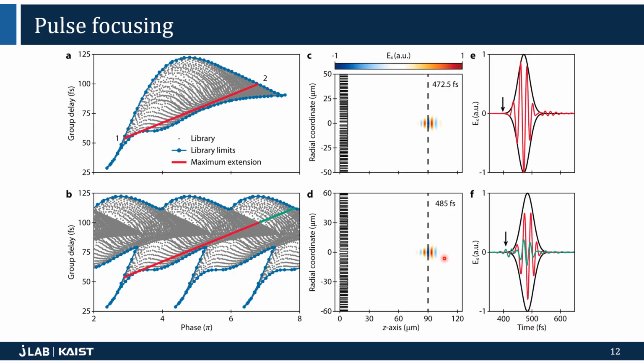But we also see a slight elongation of it. We attribute this to 2 reasons. First, we have an abrupt phase jump in the B-type lens system. This could cause irregularities in the wavefront. Second, the meta elements from the extended part of the library, we found that these exhibit less ideal wave transmission behavior due to the excitation of higher order modes. It is, however, not particularly strong. However, these things should be considered if designing metalenses for pulse beams.